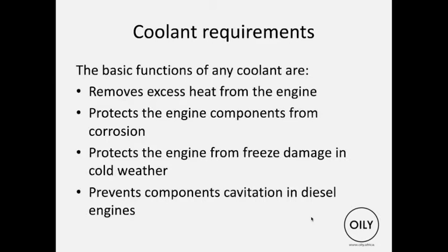Basic functions of any coolant are to remove excess heat from the engine, to protect the engine from corrosion, protect the engine from freeze damage in cold weather, and prevent cavitation in diesel engines. Well, any engine really.